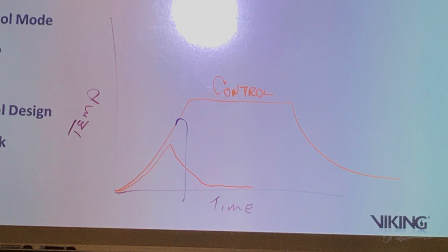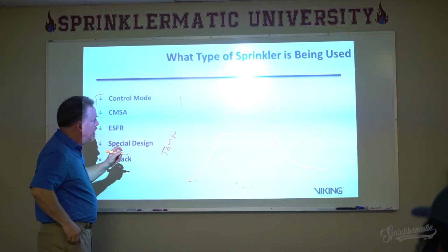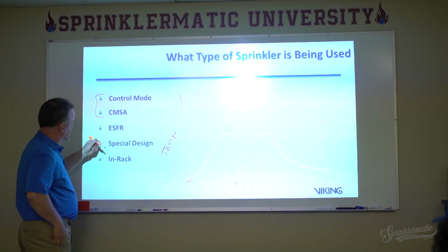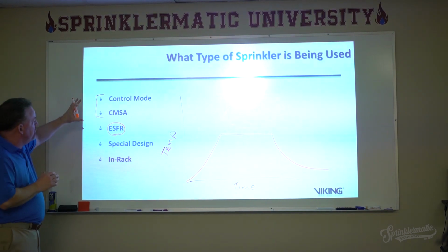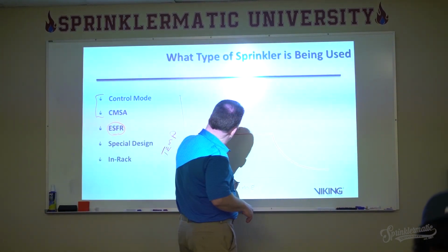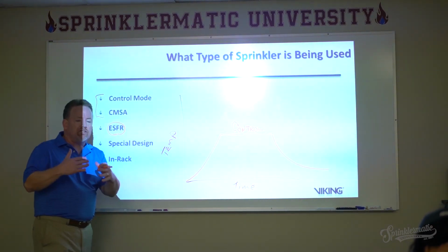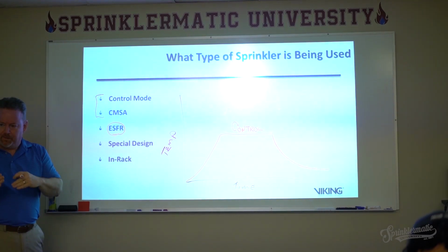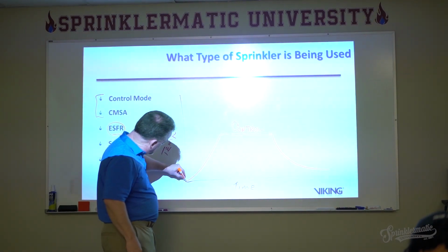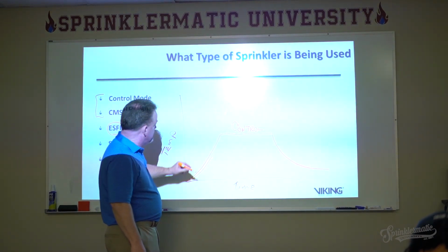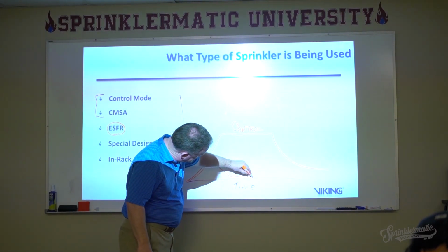In the 80s it started, and in the 90s it became even more prevalent: we came up with an ESFR sprinkler. So we went from this control mode up here to actually being able to suppress the fire, putting enough water on that fire so that, as it took off, the ESFR sprinkler would kick on and you'd go down to this.